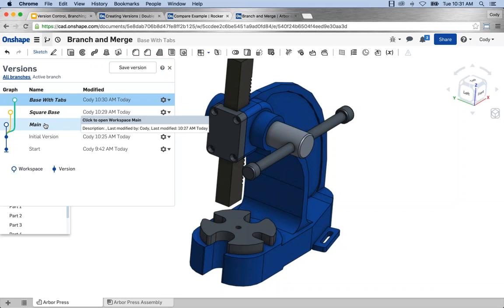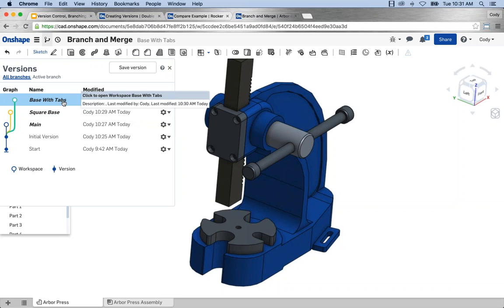So I wanted to discuss that whole process. But again, important to point out, if all you're trying to do is build variations of your model, creating branches is enough. You have these independent places to modify it and not worry about affecting each other. Also very useful, for instance, when I share a document. If I share a document and, for instance, two people want to try out different design variations, two branches for each person is a great way to do that, to establish that. So a number of different examples I could give you for branches, but just realize that you do not have to merge. You can create as many as you'd like for all the different design variations that you'd like.